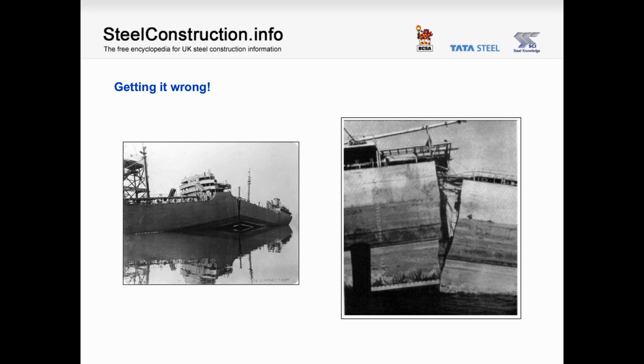When the temperature of the steel drops below a critical point, the mechanism of failure changes from ductile to brittle. In simple terms, this was a brittle fracture issue due to the incorrect specification of the steel subgrade. In riveted ships, the same issue may well have existed, but any cracks would stop at the next rivet, and so defects could be detected and remedied.